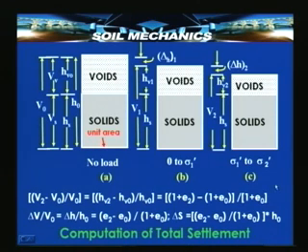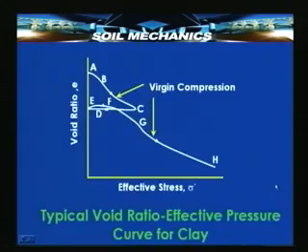Now, we shall close here today. So, with this, in today's lecture we have seen the consolidation phenomenon in very great detail and understood it to be a phenomenon that takes place mainly in saturated clays due to expulsion of water, which takes place in all probability very slowly because of the low permeability of the soil. And we have also seen that it is possible to compute the total settlement by doing a simple laboratory experiment called the consolidometer or consolidation experiment.